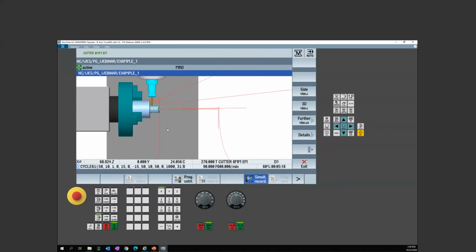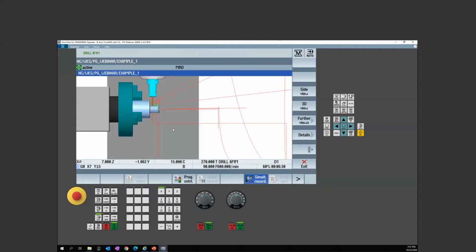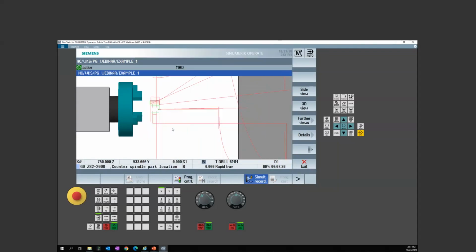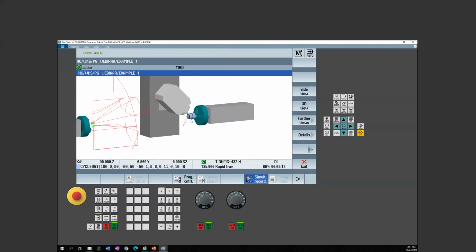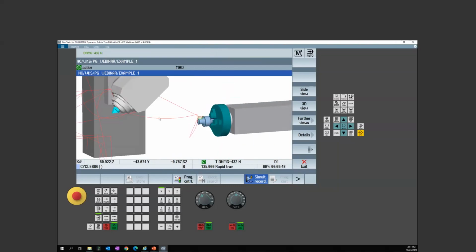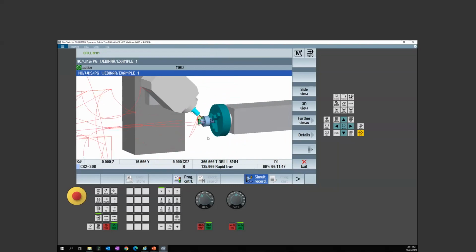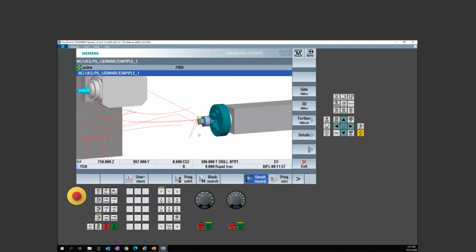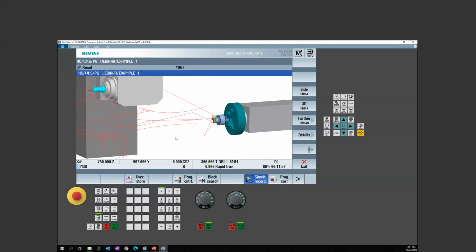So we are going to do a part transfer. This is where I was saying I'm not going to spend a lot of time describing it. Check out that webinar, but there we're going to grab it and jump over to a part transfer. Then we'll flip over to a neutral tool and do some different orientation changes while turning. We're going to do a little bit of milling on a compound angle and some drilling on a compound angle. So this should really start to get you down the road of working with B-axis technology when we're all said and done. So let's take it a piece at a time, kind of chunk it out.